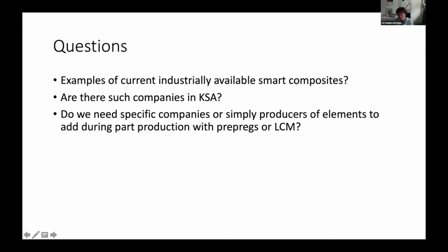So either you have to accept that the part is not of very high quality in terms of the consolidation, or you need to post-process the part. So either by having rollers when you print, a bit like AFP in the end, or by having post-processing in a press, for example, in a mold afterwards. So at the end, it becomes very close to a classical tape placement, but with a thinner...